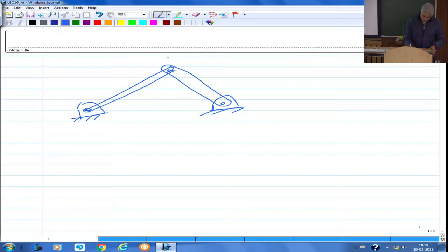Usually what we do in case of truss, of course, we consider the forces at the joints. So if there are any distributed forces also, we approximate them and take them at the joints. So with respect to this member, these two forces will give rise to axial as well as transverse force. Similarly, for this also, these two external forces will give rise to axial as well as transverse forces. But then whether we should go for modeling this using frame element or truss element, that's the question.